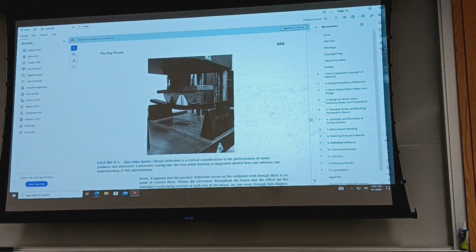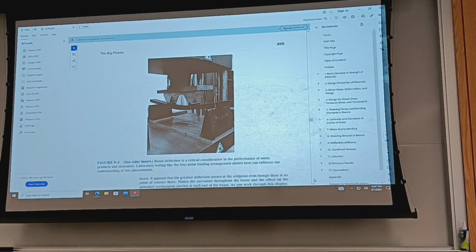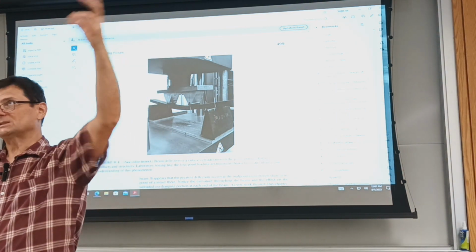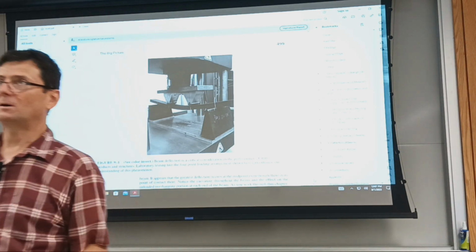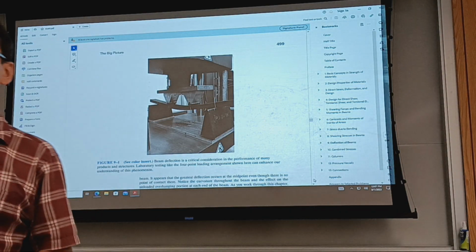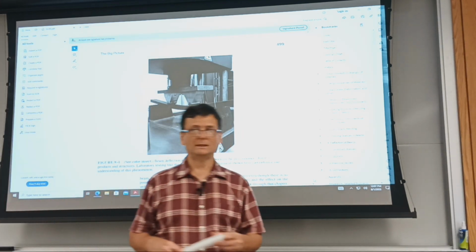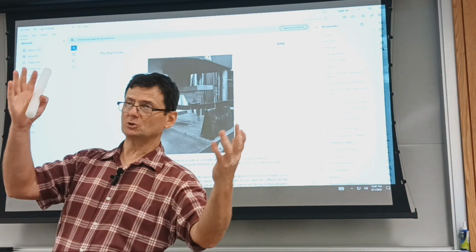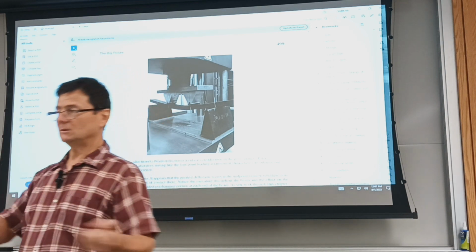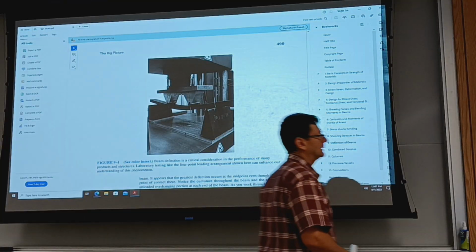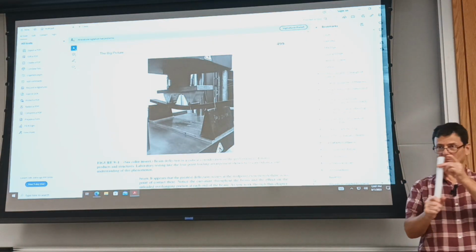So it's the same with the tuned mass dampers. They are assembled of concrete slabs, and some are suspended on cables, some are floated on hydrostatic bearings, pneumatic bearings, and there are actuators that sense the motion of the building, and they move that mass on top the right way, the opposite, and you can dampen the oscillation.